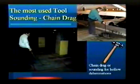All right, let's get into a couple of tools. The primary tool for listening for deteriorated concrete is right here. It's the chain drag. It's not very sophisticated. You can get it at Home Depot for a couple of bucks. You can see over here is another type of chain drag. This is actually an ASTM standard. We now have an ASTM standard for doing a chain drag. So you can make it.